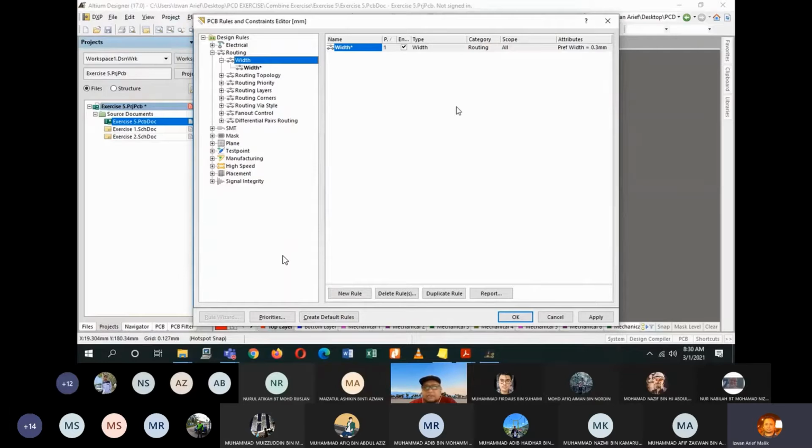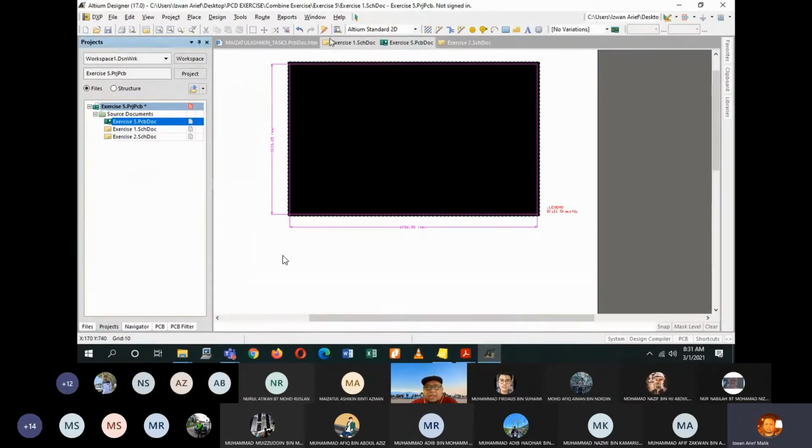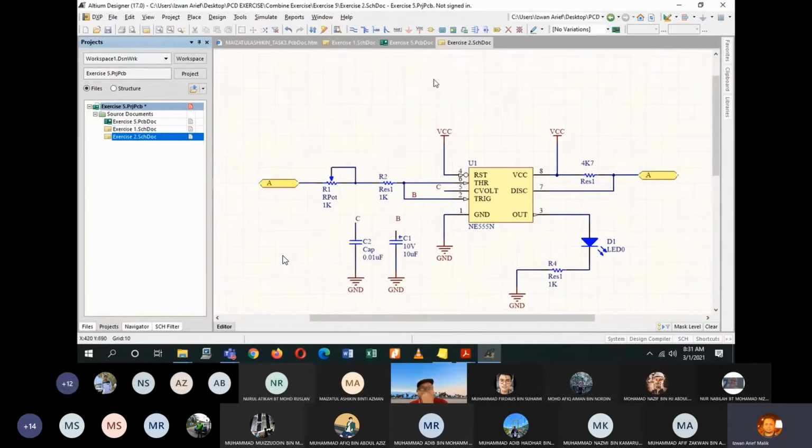So we will give the name of the VCC and ground. So let's say if I name the VCC here as VCC, then the circuit that used plus 5 volt earlier will not have a connection. So that will become an error. Okay, so make sure you check first that both the VCC and ground names are the same. Alright.